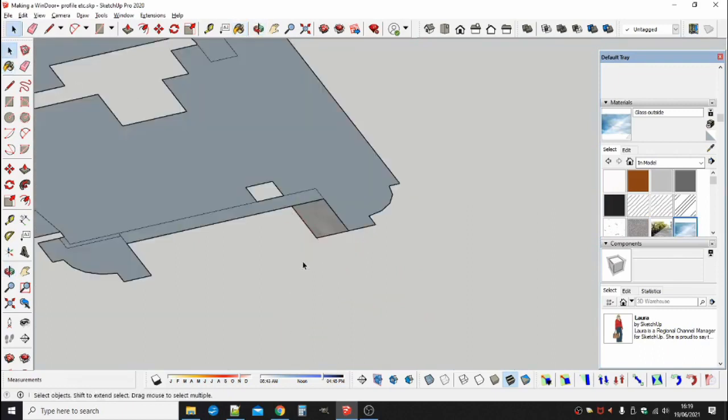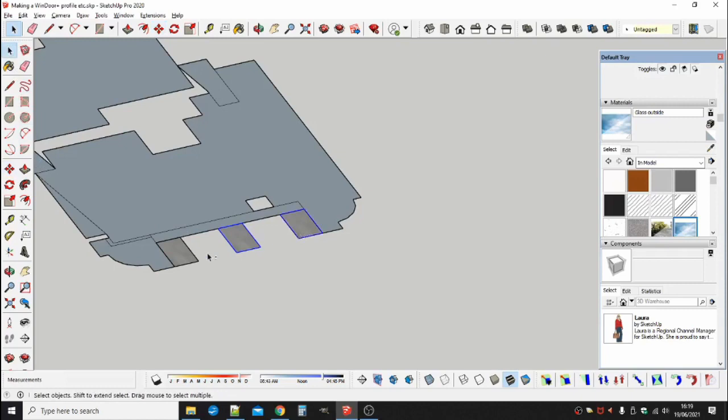The back face can be painted with one transparent glass texture and the front face with another. If the sash is to be a spandrel panel, then use opaque textures for the front and back faces. The textures you choose will be painted onto the front and back faces of the outside and inside faces of the glazing unit in the finished 3D window. Just copy the group to the other glass sheet locations when you have finished painting it.